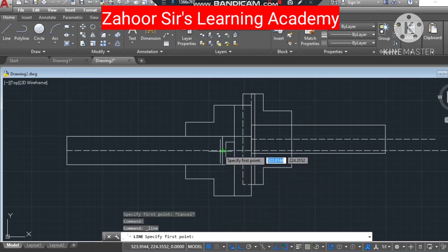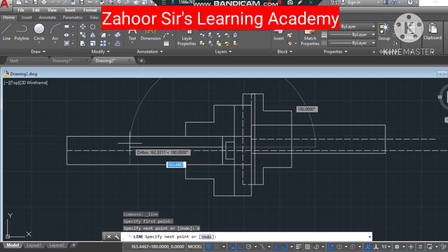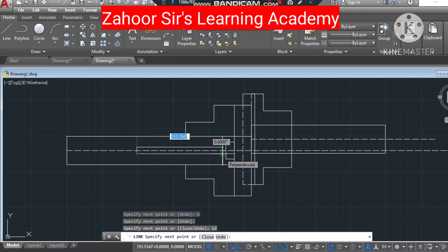From here, because that's a square key, I will first select this point by pressing the left key, then I will go 6 mm above, then pressing enter, then I can draw a key. So this much I can draw a key, and then pressing there, then I will write 12 mm and connect this point with the key. So that is how I have to show the key.